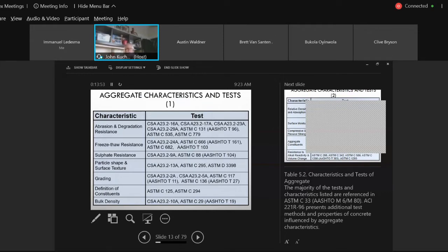So anything below grade, piles, grade beams that are buried in our high lacustrine clay soils automatically use HS cement, high sulfate cement. So in other words, if you were building a house or you were pouring piles for a building, let's say you're working as a project coordinator, concrete's coming to the job site, casting piles, caissons, whatever the case may be. If the contractor orders the concrete, he may have forgotten to say, I need a mix with HS cement. But the ready-mix producers are so knowledgeable now in the Winnipeg area, it's just standard. Anything below grade, they'll say, okay, it's an HS mix.